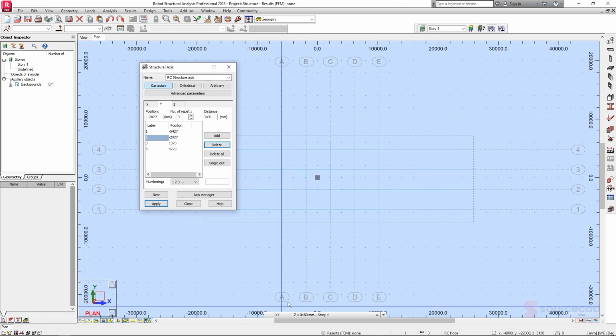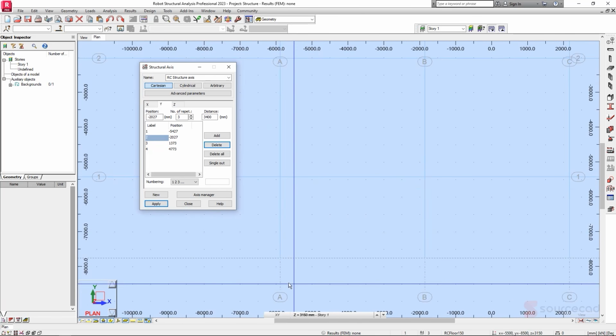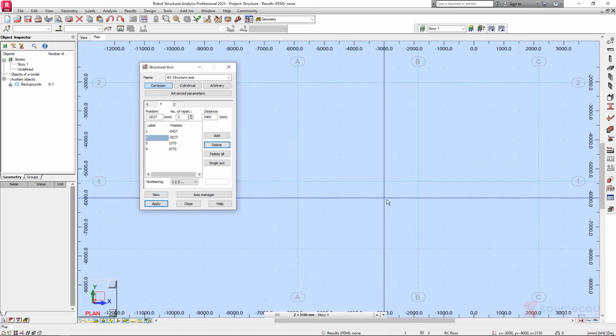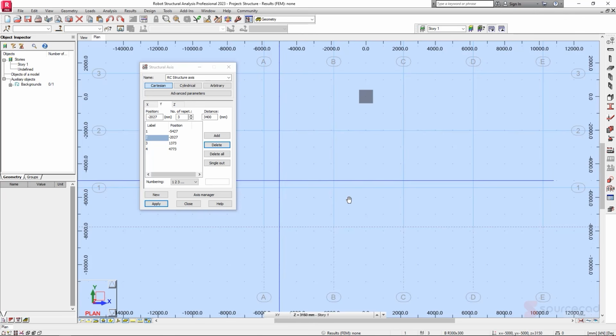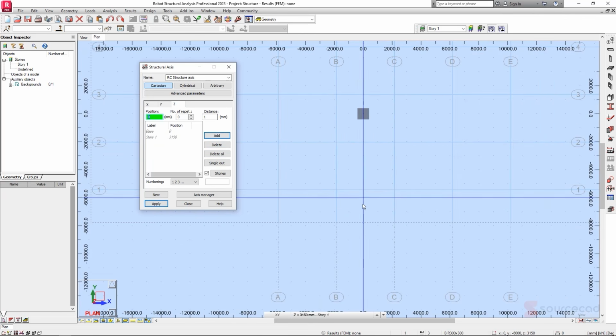And the way to read it, it's A1. So this is A1 grid. And if you zoom in, our axis tends to come closer. So A1, B1, like so. So having done that, now let's specify for our Z direction where we have our story height.